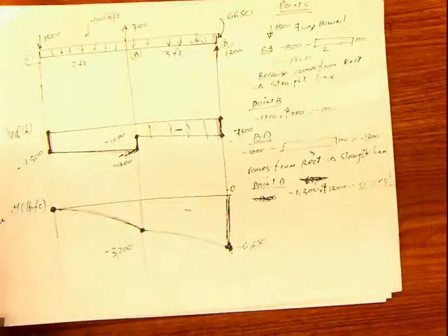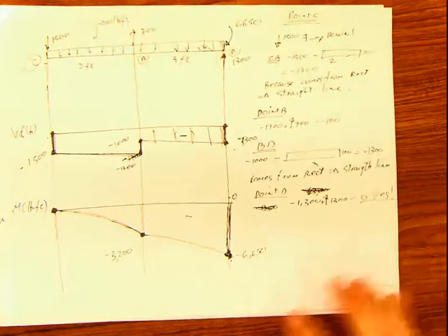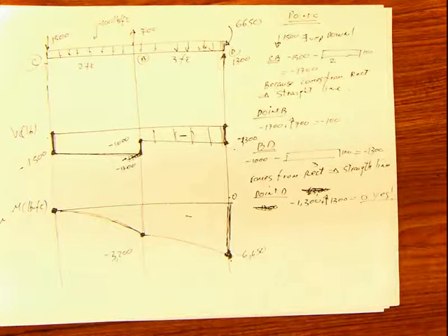So it doesn't hurt calculating the reactions. Actually, it helps a lot because it tells you if what you're doing is correct or not. But if you are in a rush and you don't have time to calculate those reactions, at least in that particular case, when you start plotting from the other end of the reactions, then start doing it and don't calculate the reactions. But usually I hope that you have time because you are practicing a lot.